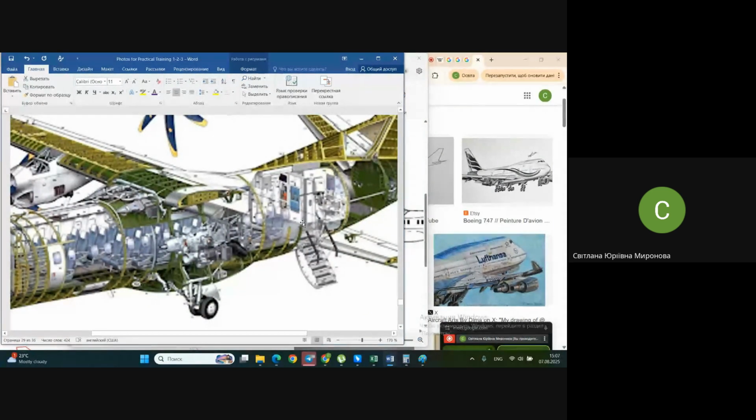That wing is continued practically through the fuselage. It's continued to the other half. And these two halves meet in the middle of the fuselage, and it has the same structure here, this center wing, as in the wing itself. And you understand that is practically the most bent place, the place where we have the maximum bending moment. And this place is very massive.